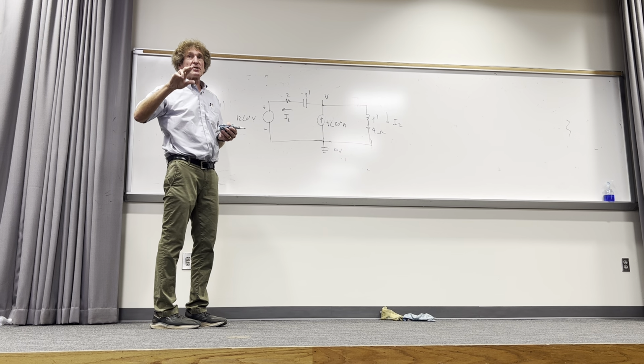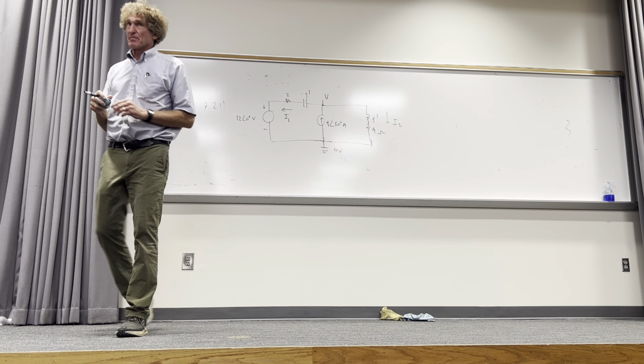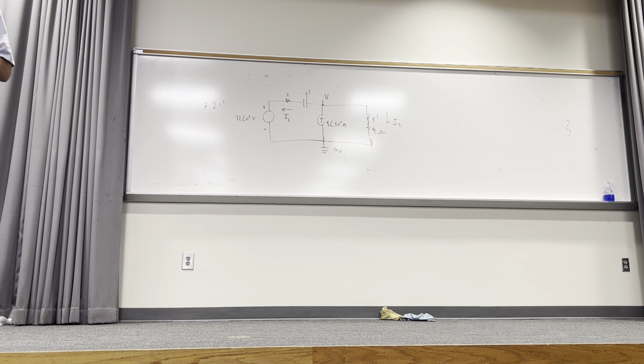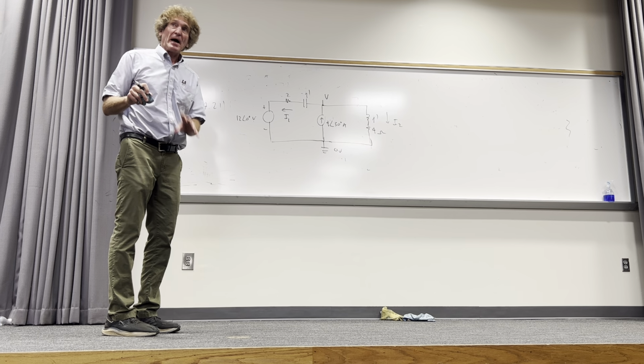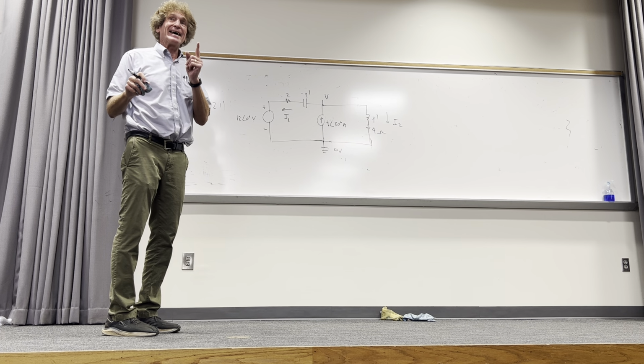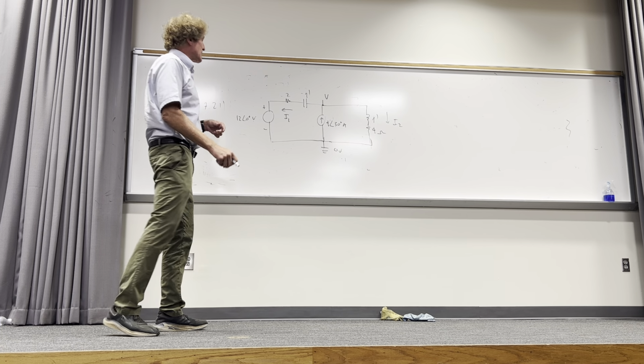You can use mesh. We could do it with mesh too, but the reason I'm saying nodal, for the most part, with very few exceptions, nodal analysis has the minimum number of steps, usually, if you need all the currents and all the voltages. With mesh, sometimes you have more steps, and you can have a larger matrix. Now, the easiest possible way, if we want just the power associated with one element, would be Thevenin. I'm leveling with you, that's the way to always go. But in this case, we're doing this.